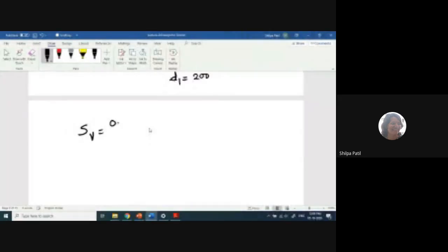So it is 0.87 into Fy. I will assume 415 only, because we can use the twisted bars also as stirrups. Multiplied by ASV, which we have already calculated. What was the value? Area of the stirrups, 100.53.